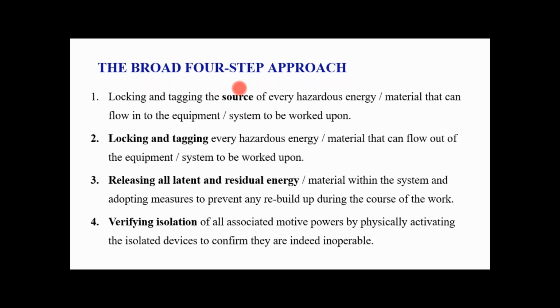Whatever the source of energy, be it mechanical, electrical, chemical, radioactive, thermal, etc., we have to lock that source and apply a tag on that lock for the repairing, modification or servicing work. That is the first step of the LOTO system.